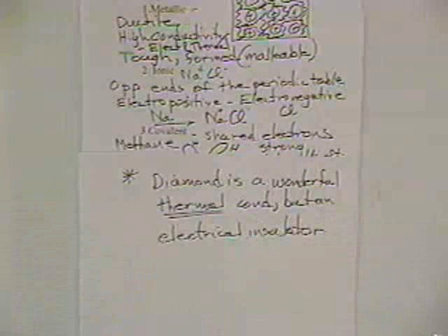So there are thin film applications where you use diamond in various devices to get the heat away, but provide the electrical insulation. But most covalent materials are both electrical and thermal insulators. And there's a picture of ionic and covalent bonding on page 10 of the notes.